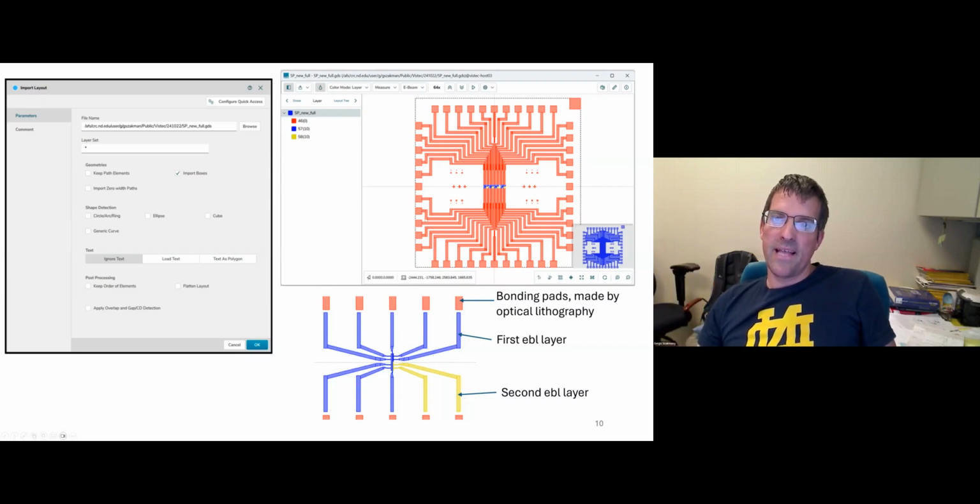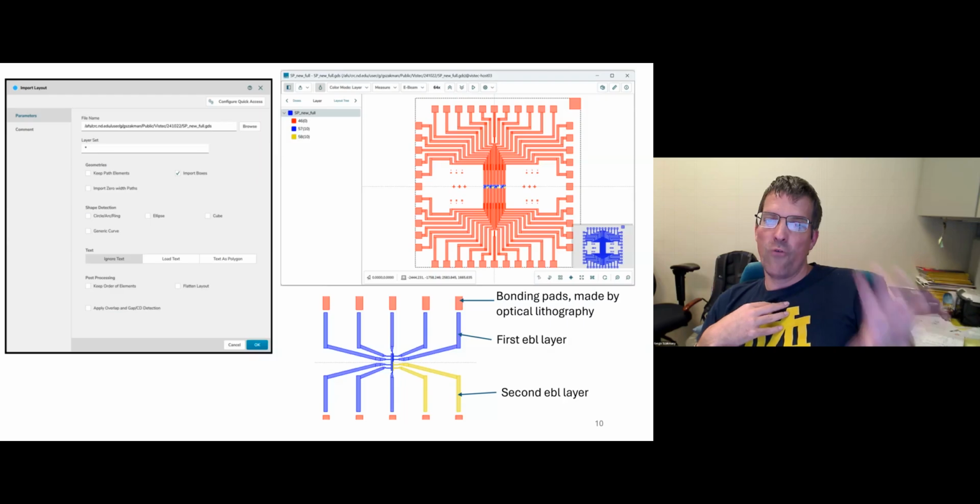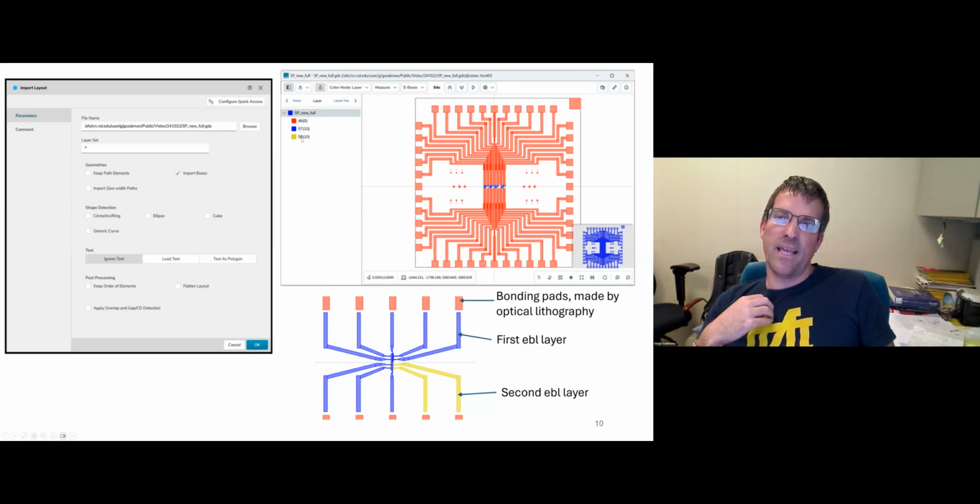It's because in that case, you can see your whole pattern imported into Layout BEAMER. And it gives you a much higher control that your different layers, as you move through the conversion, will be exposed at the exact same coordinates, so your overlap and alignment won't be messed up. So, for example, I imported this file in here, and after importing it, you don't really need to change anything on this tab. You can see that there are 3 different layers.